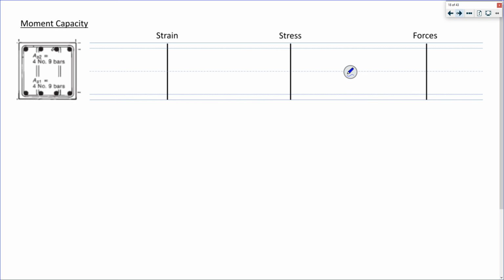So, our final spot, we're going to ignore the tension because these are columns and they have compressive values. So I'm going to ignore the tension. My last point on my curve is my moment capacity. This is moment only.